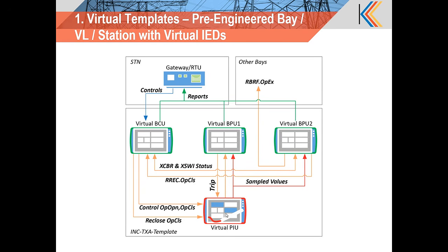So you can make various design choices as to how the secondary equipment has to perform its function, and you can do this by creating virtual bay templates with virtual IEDs. But creating a template is not very much useful if you're just going to use it as a reference at the time of actual system integration.